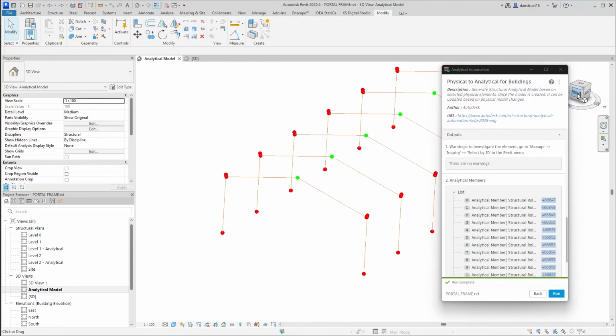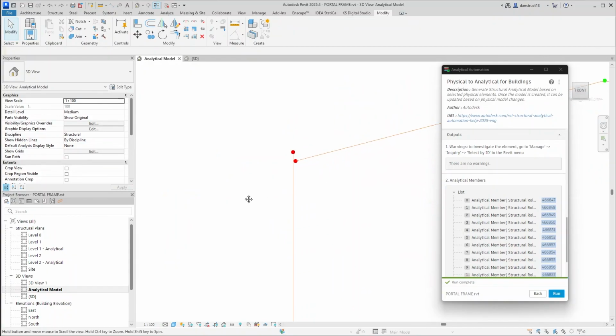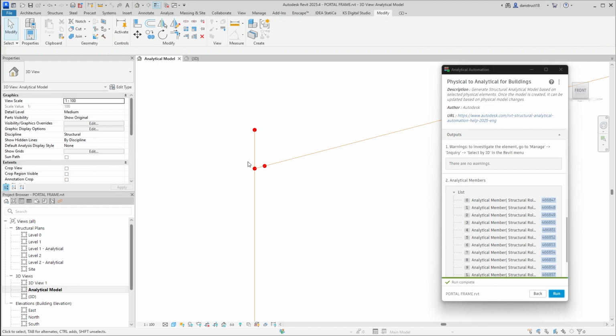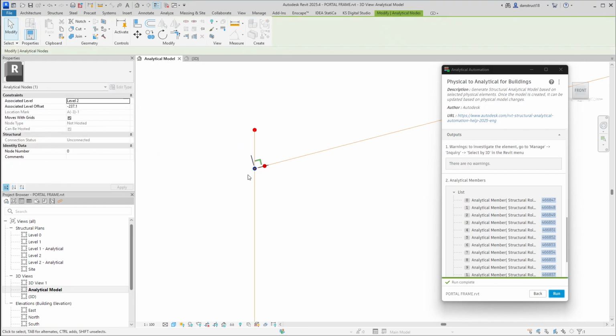First of all, I'll switch over here to the front view. And to connect this rafter to this column here, I'll go ahead and select the node. Now I'll move it according to this red line here in this axis. So I'll click on that grip point and then just drag it in the straight direction until it intersects with this column. We can see even with that as well, that node is unconnected.